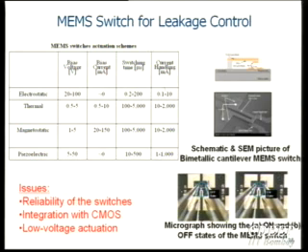We looked at electrostatic, thermal, magnetostatic, and piezo kinds of switches. It turns out that for the kind of applications we're looking at, the thermal switches were actually quite good. And we looked at 3D integration of these switches. As I mentioned earlier, these are some of the SEMs of the bimetallic cantilever MEMS switch that was developed. Issues certainly are the reliability of the switches, integration with CMOS, and low voltage actuation. CMOS compatible operation turns out to be important.